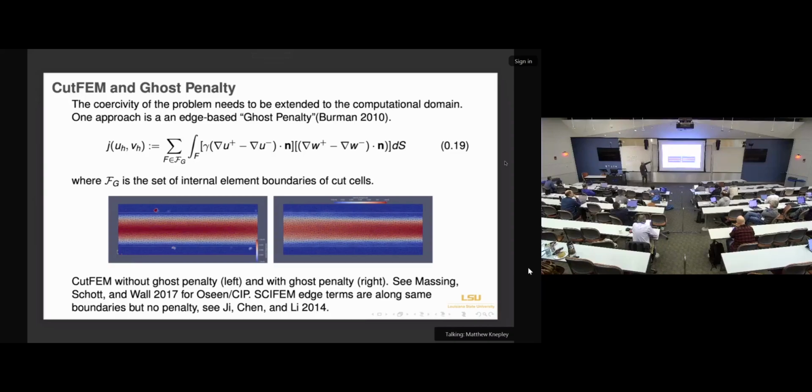So this is the last step that you need for those schemes, which is when you apply something like the Nitsche method over the cuts, you have these degenerate cases where the embedded interface essentially doesn't have enough physics left to stably enforce the solution. So in this case, I've just done a simple parabolic flow with no slip conditions.